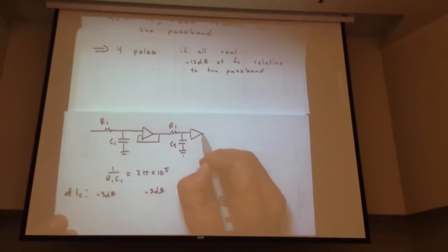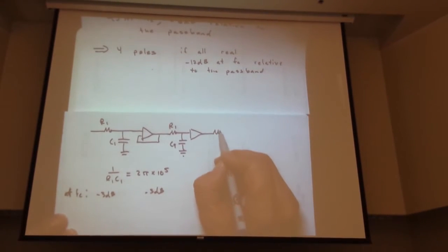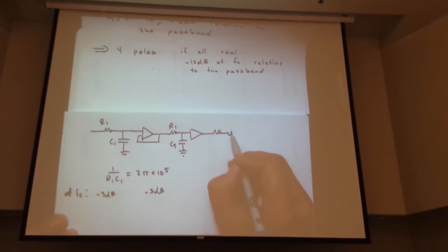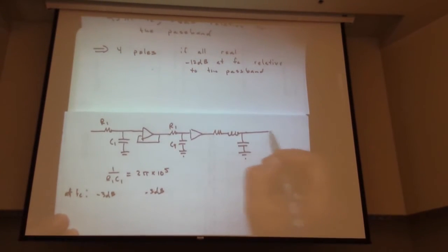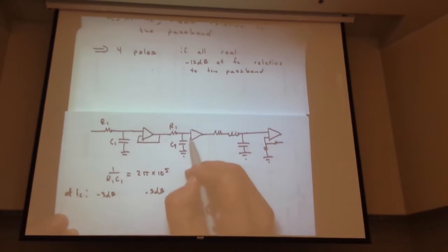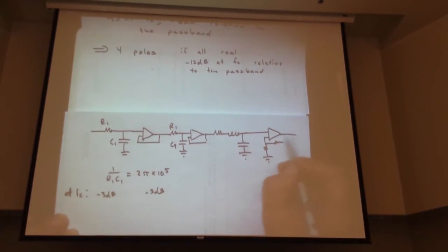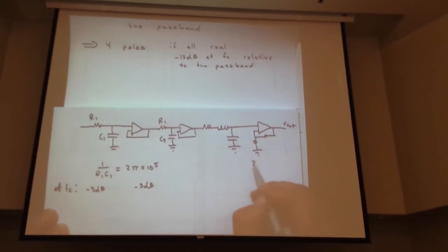So what are we left with? Well, we need an RLC circuit. And again, measuring across the cap, since it's a low pass filter. And then we also need some sort of gain. I could have put it here. I don't have to put it at the end. Here, this gives us 20 log K equals 2, approximately 2.